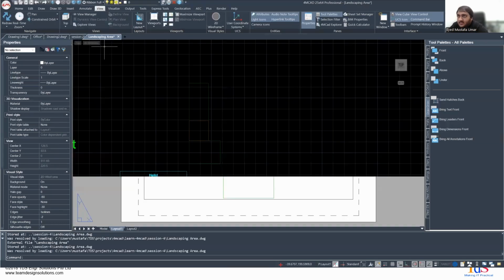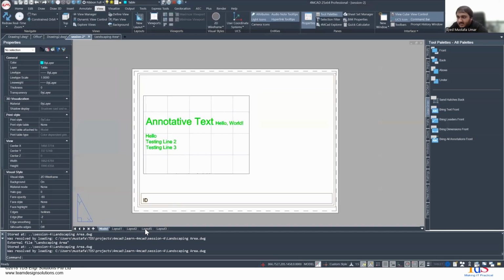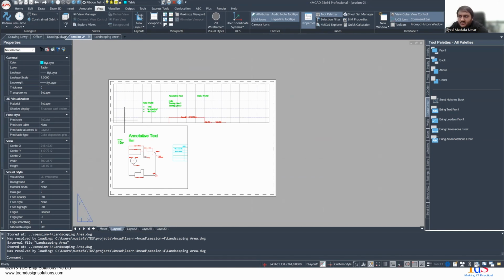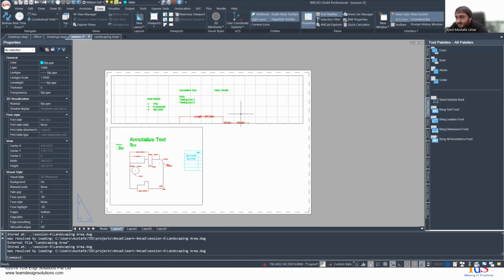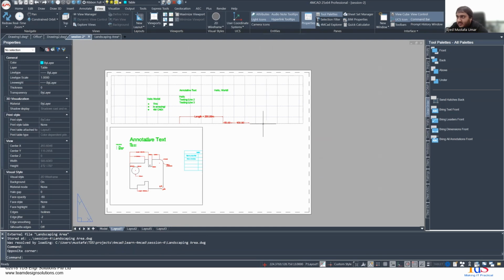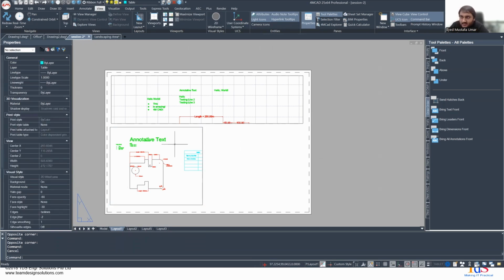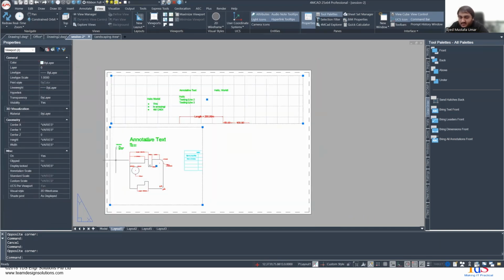Or let's go into session two for this. Or I can have something like these two viewports over here. For example, this is one viewport, this rectangle, and then this is another viewport. And I can have as many viewports as I want in a single sheet of paper. This is essentially a single sheet of paper. This is the page, the layout section, not the model section, but rather where the page paper space resides.